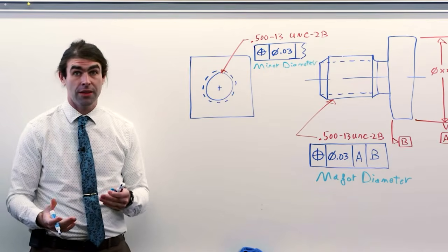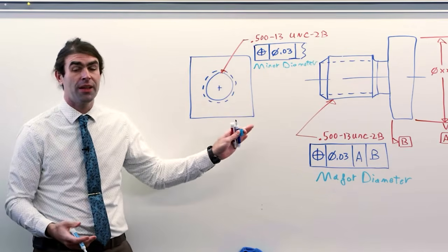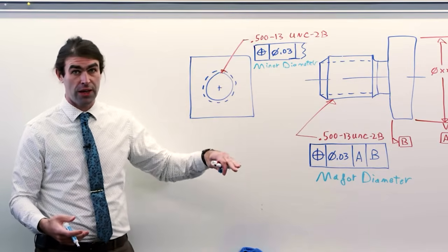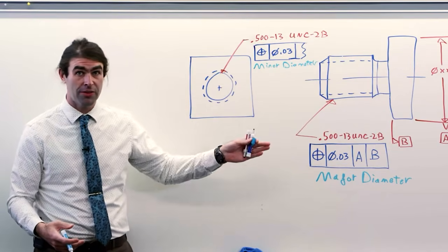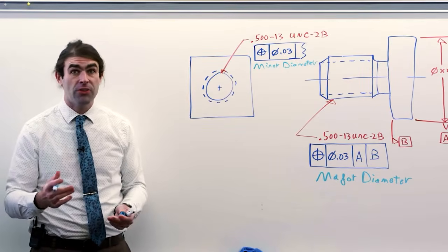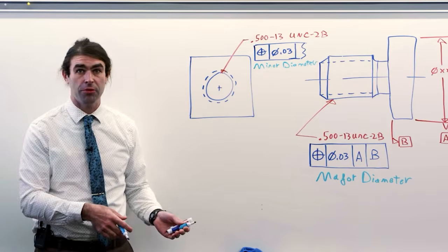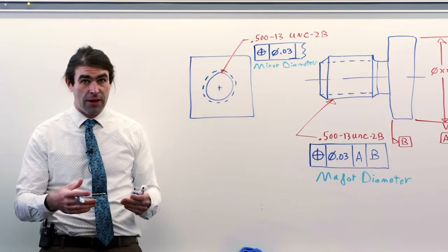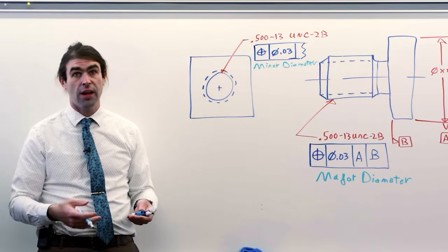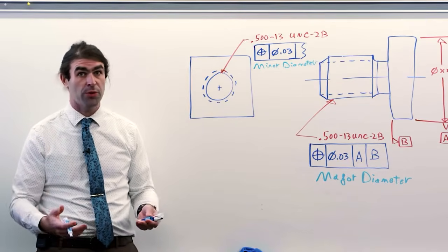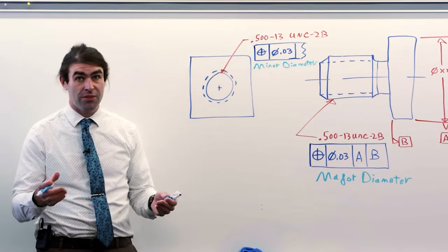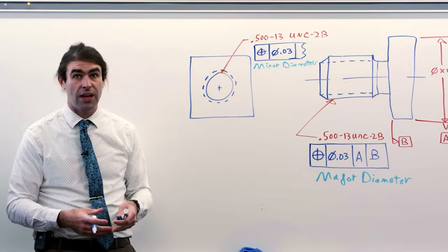Now, there's an argument that this should be the default requirement, and that you should have to go through extra effort in the design room to call out the pitch cylinder. But the ASME standard typically defaults to the least fun option or the safest option. It's kind of like how things default to regardless of feature size, which is more difficult to inspect, but typically gives you the tighter tolerances.